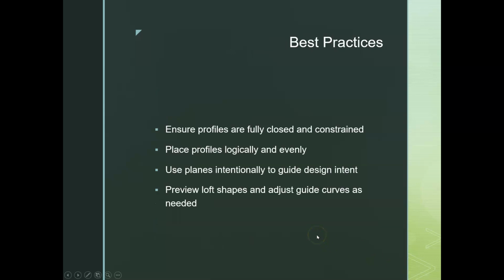And then lastly here, some of the best practices is always try your best to keep your profiles as simple as possible. That's going to help you out tremendously. When you're doing the Loft command, and this is one of the things I didn't mention, you do have to follow the Loft in sequence. If you're starting at the bottom, go to the next one up above it and keep going and keep going and keep going. If you get out of order with them, it will create a different shape.